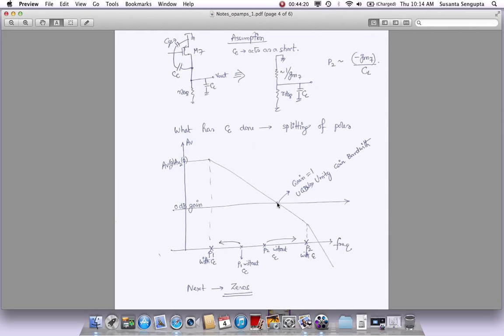So for any system, not just op-amps, if you're designing a system with two or more poles, the stability and compensation become a challenge, and that's where you're going to spend a lot of time making sure you satisfy this. There is another term which I forgot to note here, called phase margin. We have the term unity gain bandwidth, but at that point, what is the phase margin?